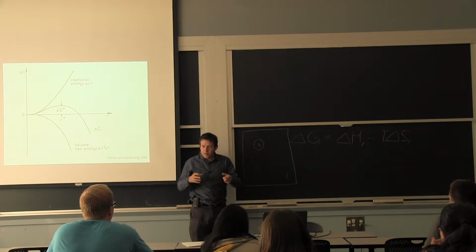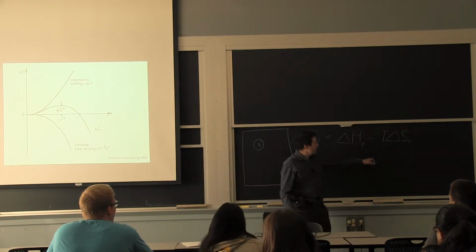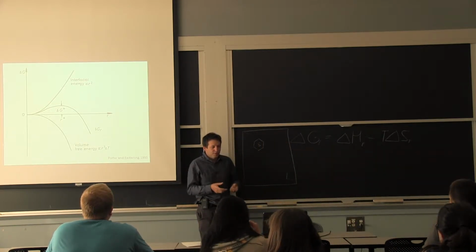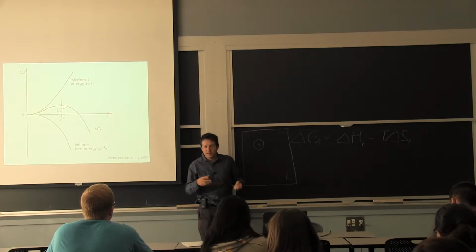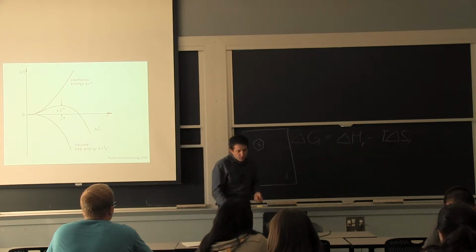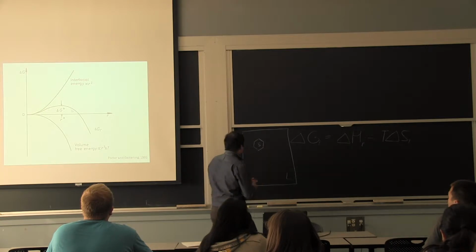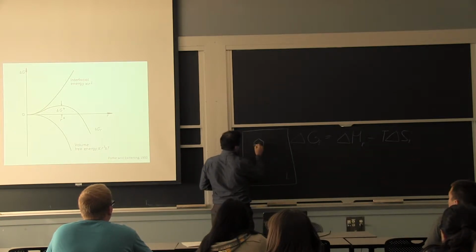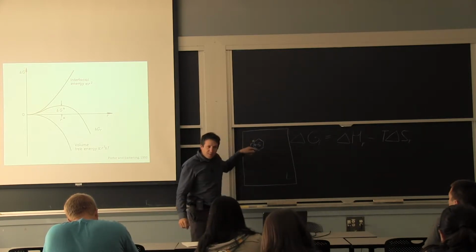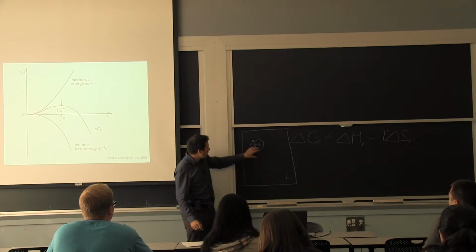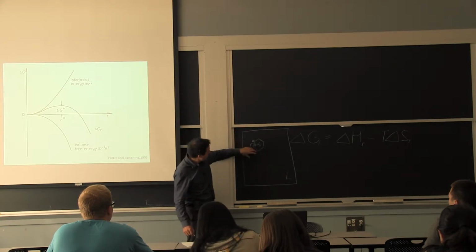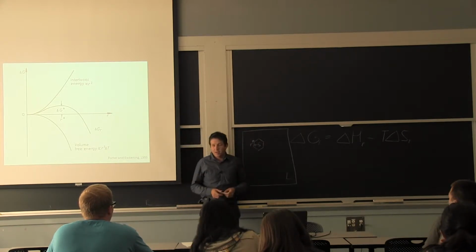There will always be a little area, oops, you know, all of a sudden the entropy is going down, the atoms are getting closer, and the question is: is this the lowest state energy or not? And then it will fluctuate backward, or it will continue to grow. So what I'm showing here is there's a critical radius, so I'll put the R on that one, the R star, where the interfacial energy is becoming less important. And overall, it's less energy to continue growing the solid than to essentially dissolve it back.